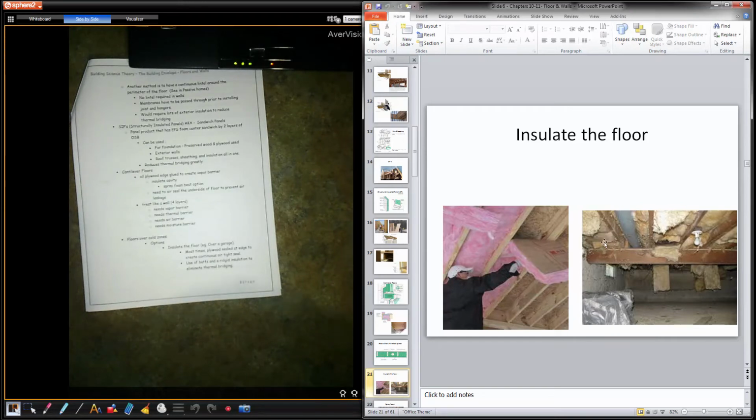What's that caused by? Difference of pressure, right? So if I have a difference of pressure between inside and outside, that means I have air movement from inside to outside. So dust from here is traveling inwards, and it's getting collected by the fiberglass insulation, acting like a filter. If I had a barrier there, that barrier would catch that particle and not clog up the pores in the insulation, making it not as effective. You can see at the far end, insulation actually falling down.